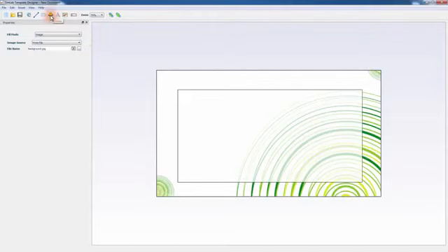Now that you're done with the design, all that's left to do is to connect the buttons to the scene states. To do so, click on the first button, and from the left panel, click on the Type drop-down list. You can select from this list what action needs to be taken once the button is clicked in the PDF file. You can link the buttons to a website, display a message box, control an animation, run a script, or call a scene state. Set it to Scene State.